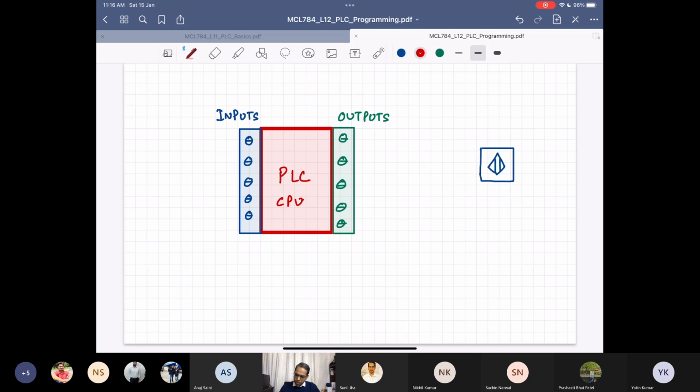So these proximity switches are electronic switches. They are inductive proximity switches, capacitive proximity switches, or optical proximity switches. We have a plus 24 volt connection because we have to provide the power supply to these switches. Then we will be having a ground over here. So this is the 1B1. If you have to use these proximity switches, I have to provide plus 24 volt, connect it to the ground, and then I will be having an output coming out of this.